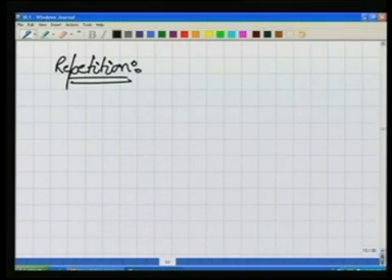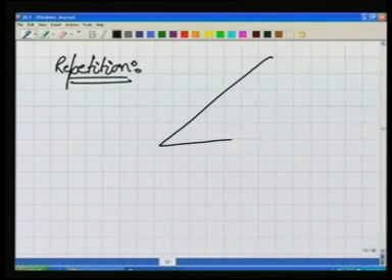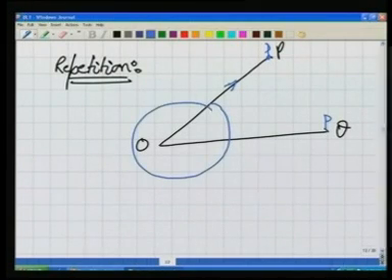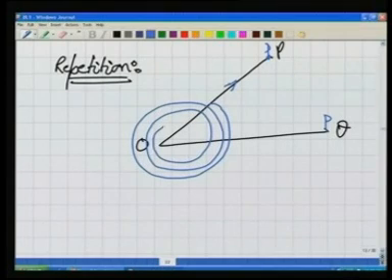Now what happens in the case of the method of repetition? If you look at the basics of the method of repetition, our observer is here, with point P and point Q. We first bisect P, the ranging rod there, and take the observation. Then we do several rounds of the instrument, because we are summing up the values mechanically, and finally we take the reading at Q, while in between, during these rounds, we bisect Q every time.